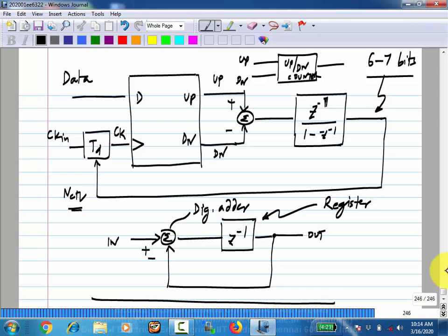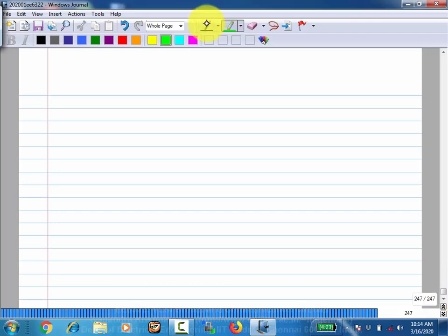So obviously there is no clock coming in from the other side. You have to generate it locally. Okay. So you take your somewhere you have some clock, and this clock could be at a different frequency than the data that is being transmitted. Okay, and then this goes through a digitally controlled delay, or a phase accumulator. You can think of it in any way you want.